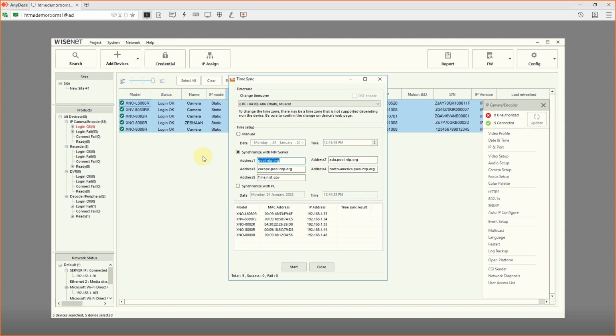But your handheld watch, wristwatch, if it is not smartwatch, if it is an analog watch, your wall clock, they have some 30-second, 10-second difference because nobody is syncing the time. No one is centrally managing the time, right? But for cameras, it is important all of them have the same time. And to make sure all of them have the same time, you can copy time from one central source, that is NVR. Okay, your recorder and camera, now both of them have same time. Whatever is the time of NVR, camera also will copy that.